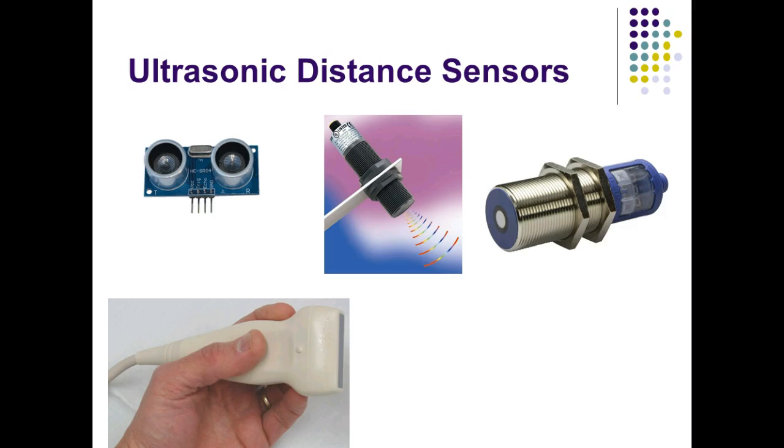Well, what it's doing is sending out pulses, but the distance can change during that time. So it would give us an output if the distance was changing, right? You understand? A digital ultrasonic sensor will only look for a distance. It won't look for a change in distance. It'll just look for a distance, right? Understand? We don't use that.